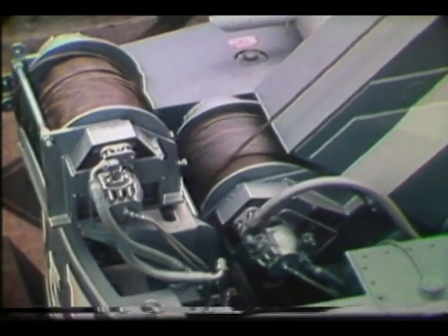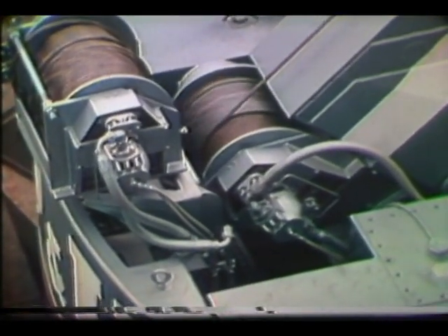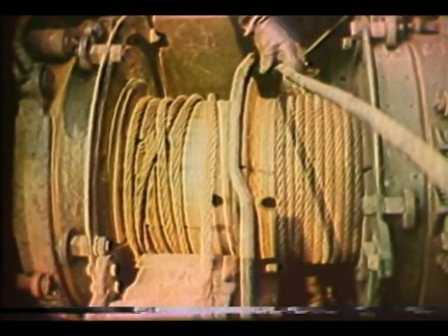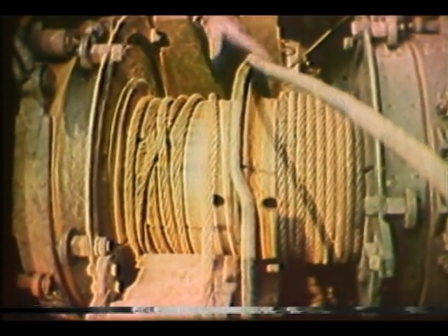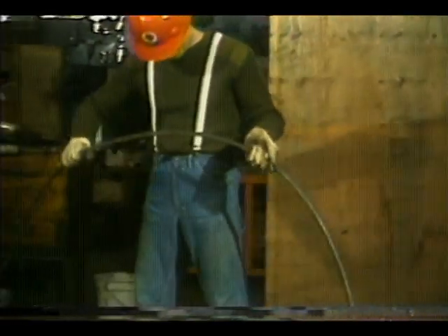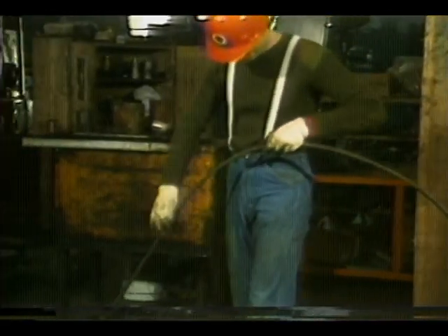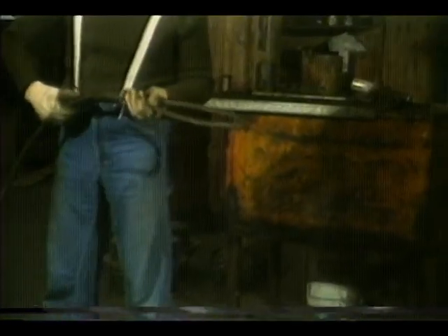Where multi-layered drums are used, examine not only the rope in constant use, but also the rope that is spooled and inoperative on the drum. Examine all ropes, including standing ropes, for possible defects caused by corrosion, abrasive dust, and erection and dismantling procedures.